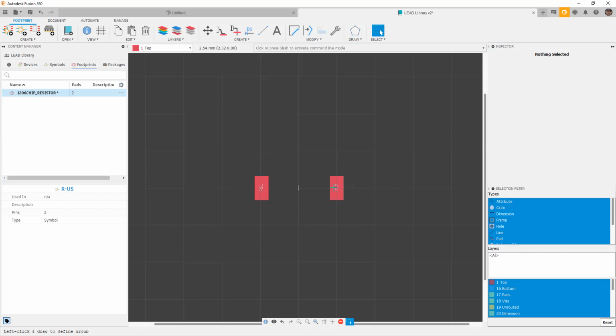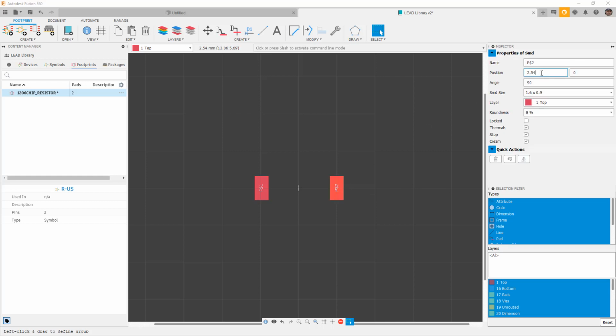And then on the other side, we're going to do 2.45. Now remember that when we're doing this, this is from the center line. So effectively what we've done is we've added that spacing, but these are still way too far apart. Now remember, we need 2 millimeters between them, but we're going from negative to positive. So each of these has to only be 1 millimeter.